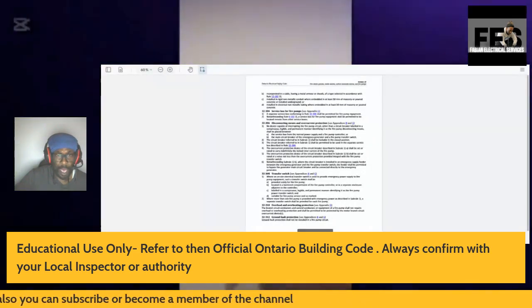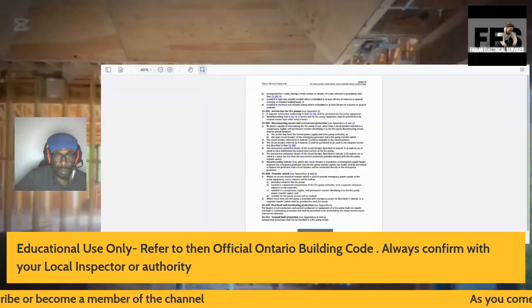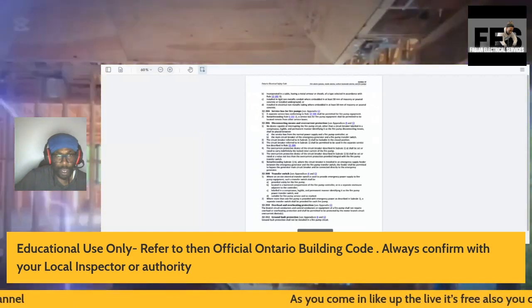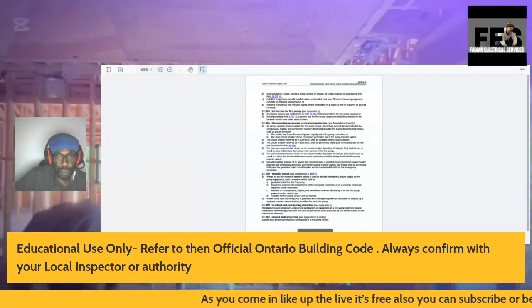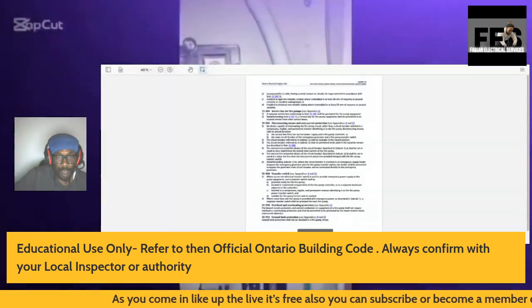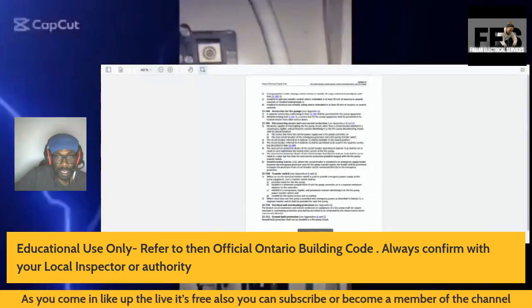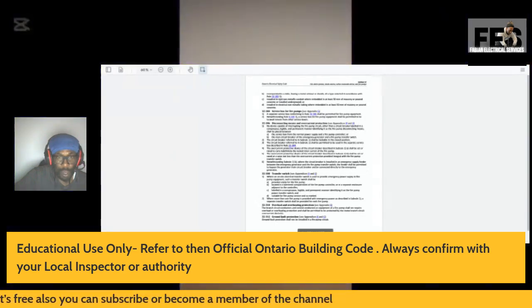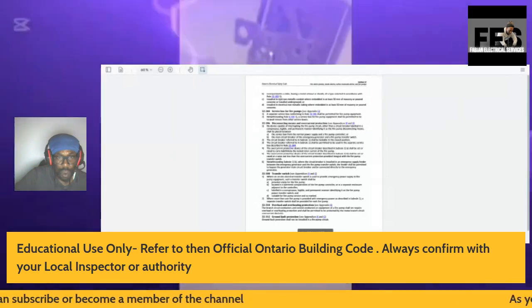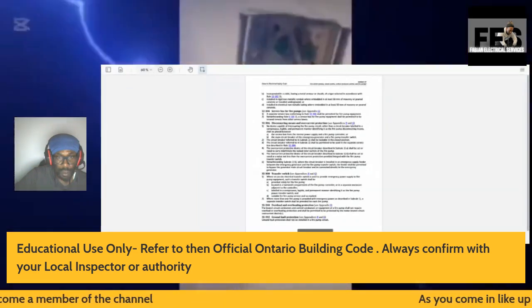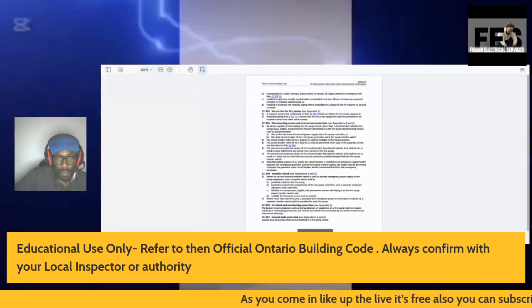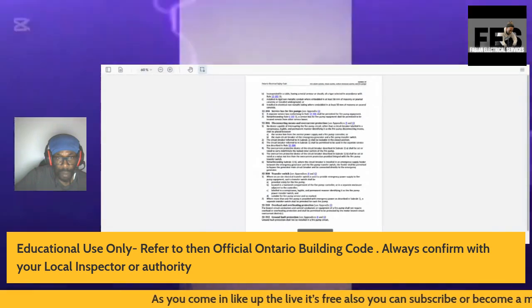So, incorporated in a cable having a metal armor or sheath of a type selected in accordance with Rule 12-102. Installing rigid non-metallic conduit where embedded in at least 50 millimeters of masonry or poured concrete, or installed underground, or installed in electrical non-metallic tubing where embedded in at least 50 millimeters of masonry or poured concrete.